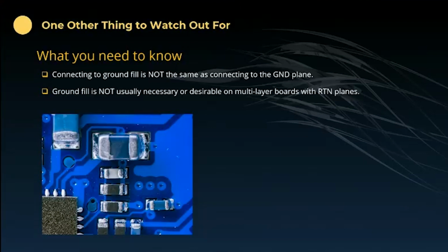And I'm just going to sum up with some other things to watch out for. Connecting, I don't like ground fill on multi-layer boards where we have solid ground planes anyway. Ground fill doesn't really help that much. And I used to tell people, if you want to put ground fill in, that's fine, but you don't need it.